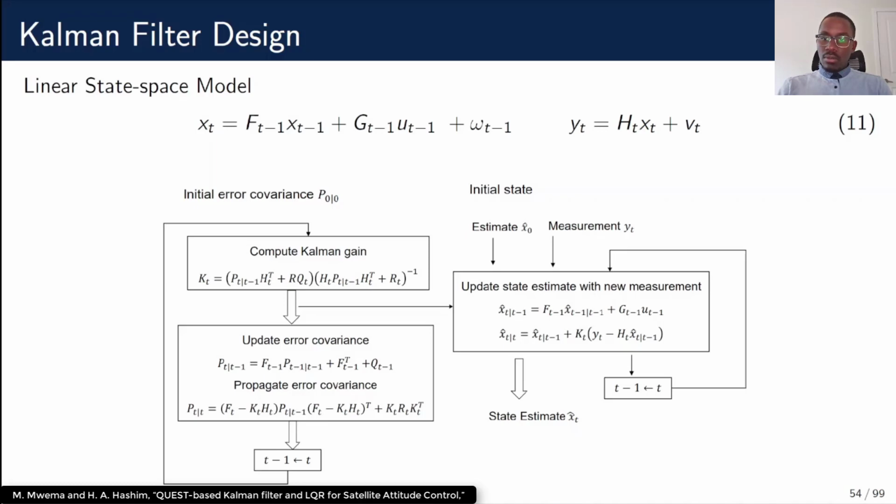The reset moves the updated information from the error state to the global attitude representation and resets the components of the error state to 0. The propagation step propagates the global variables to the time of the next measurement. This is illustrated in the figure below.